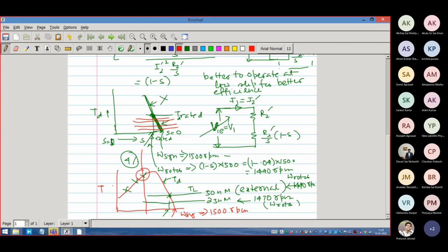You can see that the efficiency is dependent upon 1 minus S. So if I want to run it at 750 RPM, it would be almost impossible, right? It is not the way. So that's why conventionally induction machines are constant speed machines. Constant speed machine means the application is dictating. For such application you use it where you don't need to change the speed.